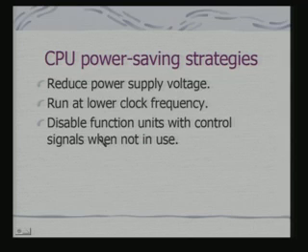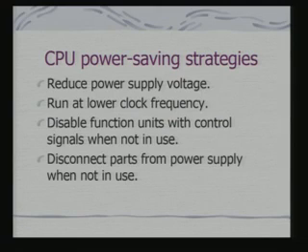The other thing is to disable function units with control signals when not in use, because the high level architectural issue is that not all units will be used for a computation. And disconnect parts from the power supply when not in use. In fact, disable is one aspect and disconnect is completely putting parts of the architecture to sleep. So, these are more the high level issues and these are more from the circuit level perspective.